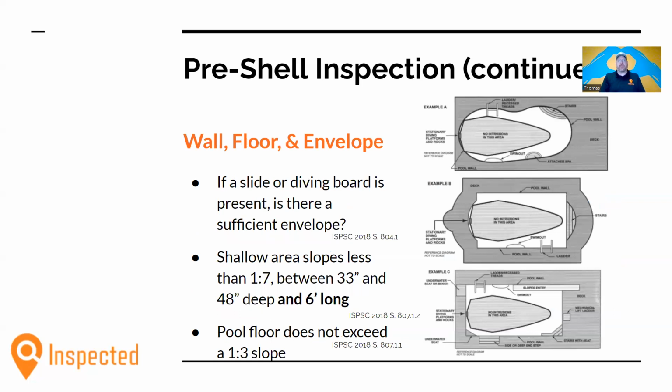Next, this code does not prevent slides or diving boards from being installed. It does dictate that they have a manufacturer-specified dive envelope, which is the width, depth, and distance a pool must be to accommodate somebody entering the pool in a diving board fashion or from the slide. It no longer is the case where builders can stack up sandbags, shoot shotcrete over the top of it, lay some penny tile, and run some water over it and call it a slide.